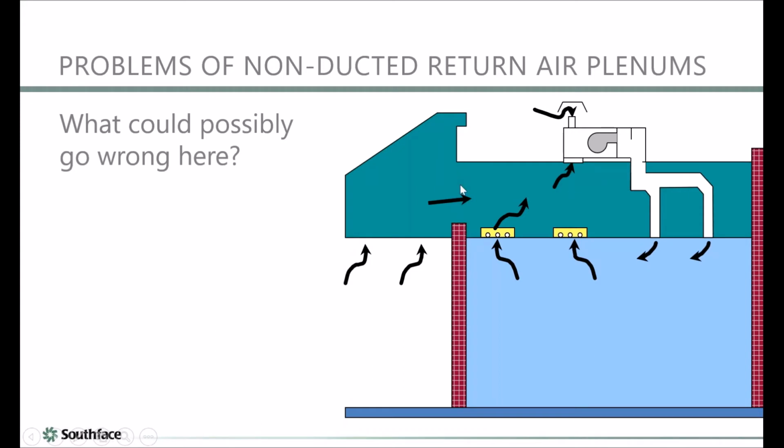And no one ever sees it, so who cares? Right, except when you make it into a plenum, now it's under pretty decent negative pressure. And often this part is not airtight. There are light fixtures out here and so on. So what ends up happening is you end up air conditioning Atlanta, or whatever city this is located in.